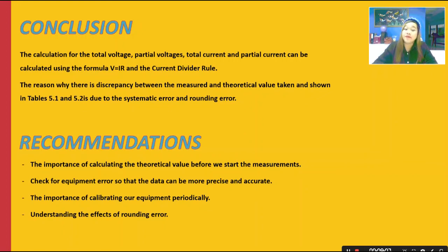Systematic error can be eliminated, not totally but to a sufficient degree, through calibration. So calibration is simply a procedure where the result of the measurement recorded by an instrument is compared with the measurement result of a standard. It's also important to understand the effects of rounding error, as errors can be magnified or accumulated when a sequence of calculations is applied on an initial input with round-off error due to inexact representation. When different kinds of number representations are used together in complex engineering systems such as rockets and missiles, they can fail catastrophically and even cost lives.